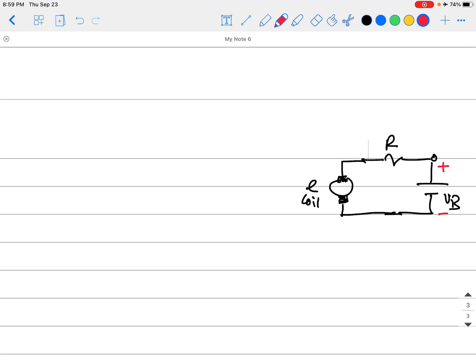And you know now this induced voltage that will be formed inside the coil, because it's moving now and cutting the magnetic field, will also have polarities, plus and negative like this, because it has two opposites. So this voltage source will force current going inside like this, and this voltage will have this polarity because it's also trying to push current in the opposite way, opposing the effect of the external source. Okay, guys? That's Lenz's law.